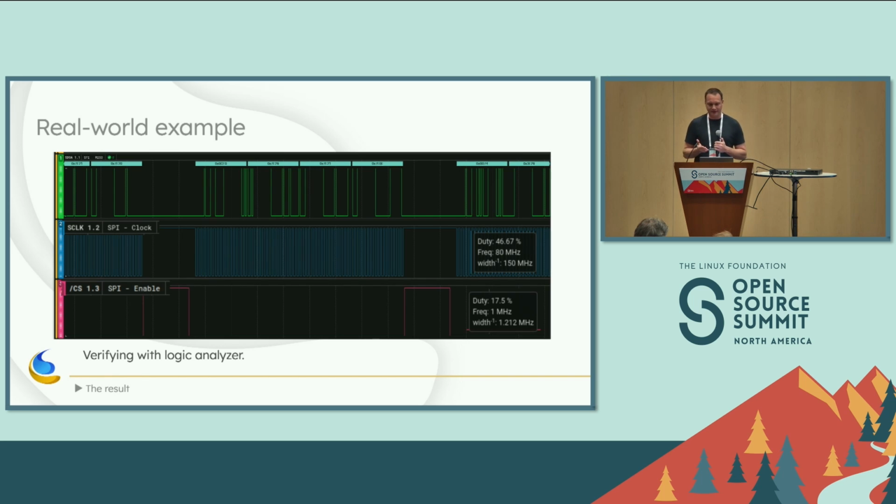And this is a simultaneous sampling, so we're actually reading 4 different things all at the same time. It's like 4 analog digital converters in one, and then the SPI bus clock is running at 80 megahertz, so that's fast enough that we can read 4 16-bit samples in that 1 microsecond time period that we have to read them, and still have a little bit of time to spare for the quiet time needed before our next sample.